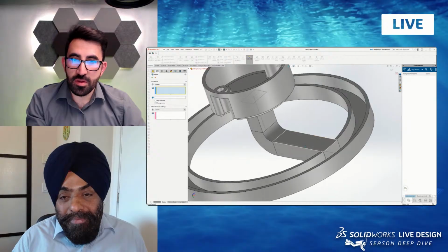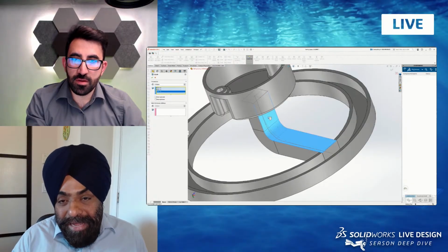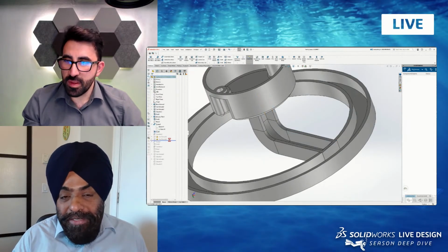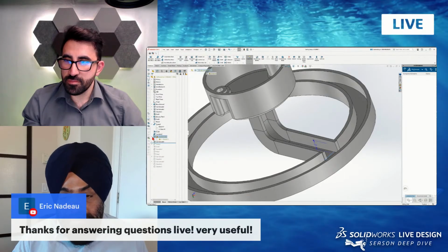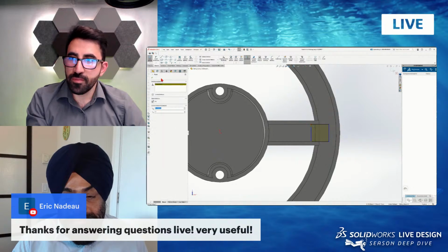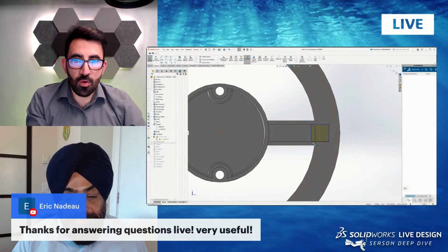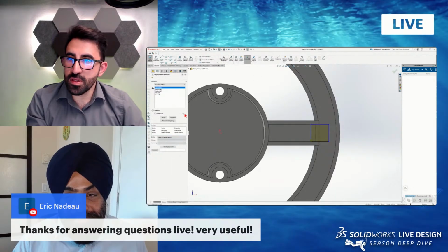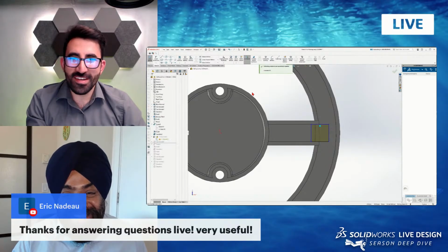The surfaces. I used to have one. I have 3. Because surfaces are regenerated, so the surface IDs are changed. Same with these 2 points. Oh, with the new SOLIDWORKS 2025, let me just try to fix this with Repair. Yeah, I like this feature. Amazing.